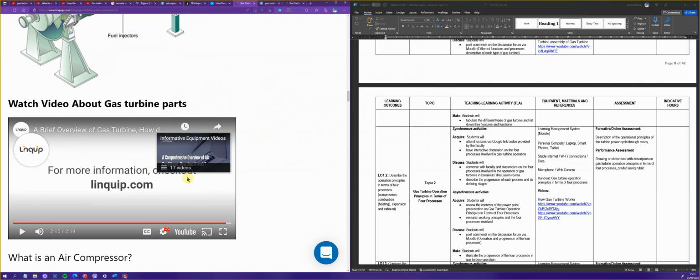Ayan. So, hindi naman siya nagkakaiba. Pero ito kasi, instead of having that reciprocating motion, direkta na sa rotary. And comparing them sa efficiency, if you will notice na mas marami pa ring barko ang gumagamit ng diesel engine, it means that the efficiency is still higher for your marine diesel engines compared to your gas turbines. Mas mataas pa rin.